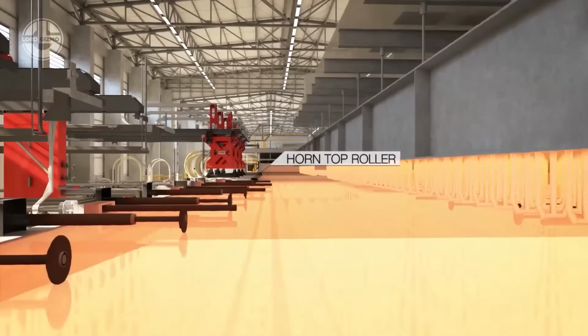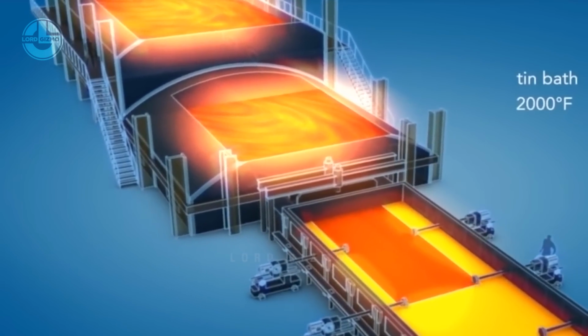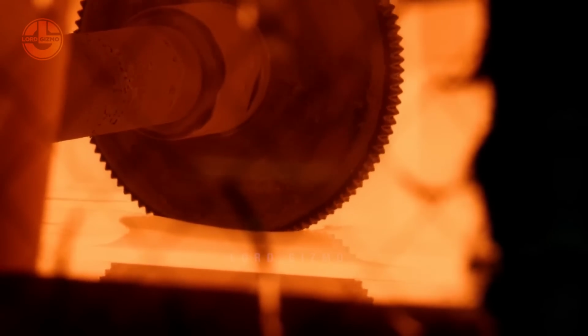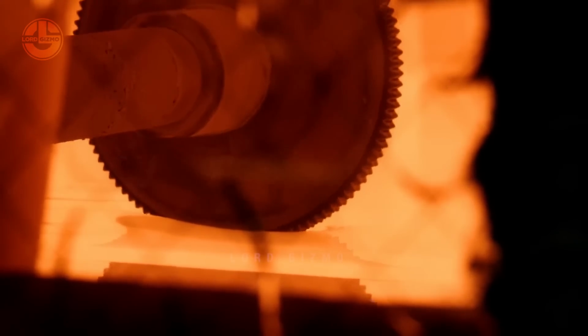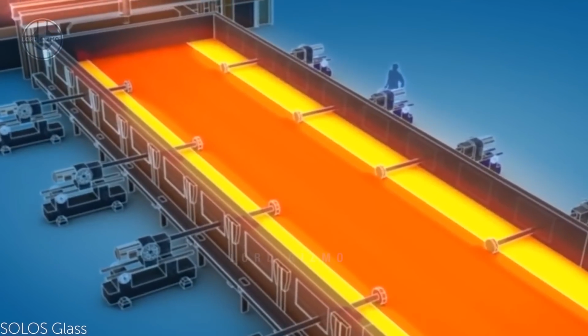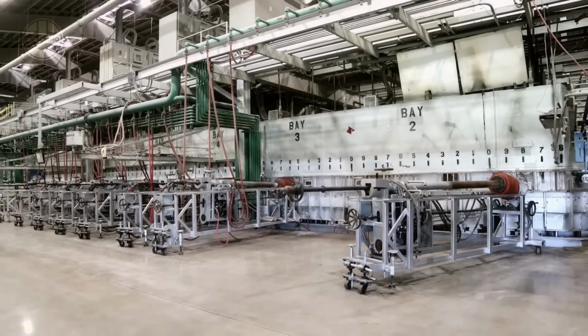This liquid glass is spread over molten tin at 2,000 Fahrenheit in a separate section. The underside of the glass floats onto the tin in the tin bath and is heated from above to form a seamless sheet of glass, usually called a glass ribbon. This process is called the tin bath.